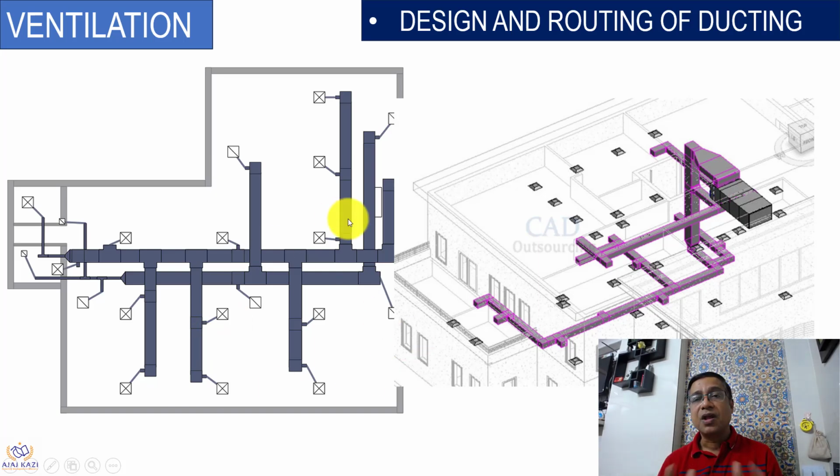You need to design a route, a proper ducting. You should see that the ducting doesn't have too many bends, otherwise it will act more resistance. Your fan capacity will go up. Look at the proper layout. See a proper smooth route.